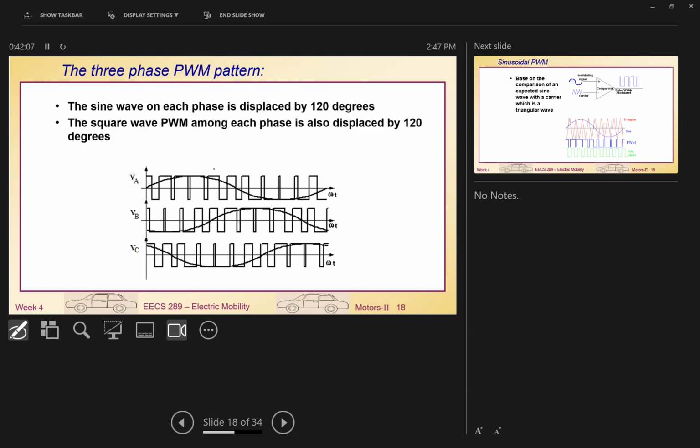But when you have a high dV/dt like this, it generates some current through the capacitance, and that will cause breakdown. So if your motor winding coating is not good enough, you will cause the winding to break down. Very often when you change to a PWM inverter operation to save some energy, the motor will get hotter and eventually break down. So you need to select motors that are workable with PWM. If in the future you want to convert many motor drives to PWM, you need to be careful about this phenomenon.